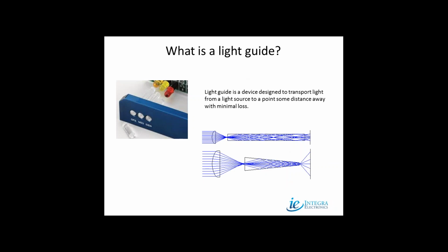Yeah, sure. Essentially a light pipe gives the engineer, the designer, the ability to take light from a source where it's conveniently located, like on a board or near the power source, and have it come out where it's convenient for the user to see it, usually at the control panel or some other place. Sometimes those things are very close together, like the image shown here, where the board's only half an inch away from the panel.